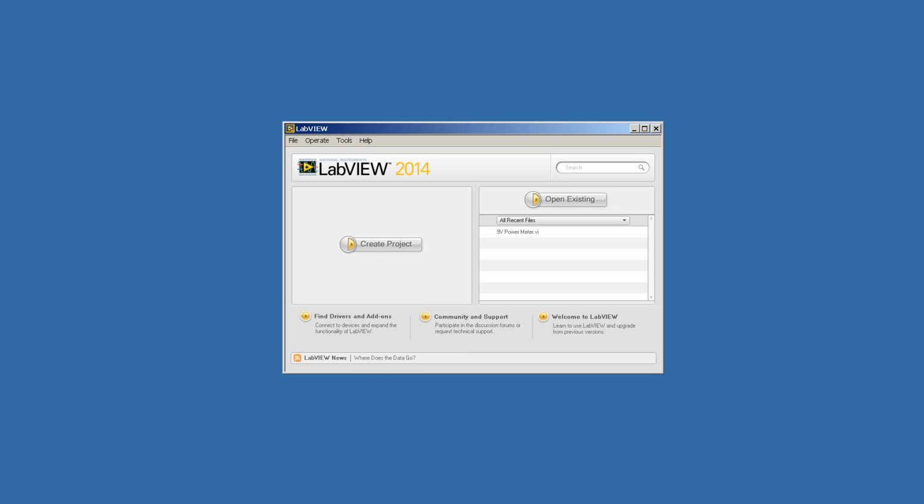The previous videos demonstrated how to use the National Instruments myDAQ device and the built-in software to operate it as a multimeter. Additionally, I showed you how we can connect the myDAQ device to measure the voltage and current from a 9-volt battery across a resistive load. The built-in DMM software was programmed using LabVIEW.